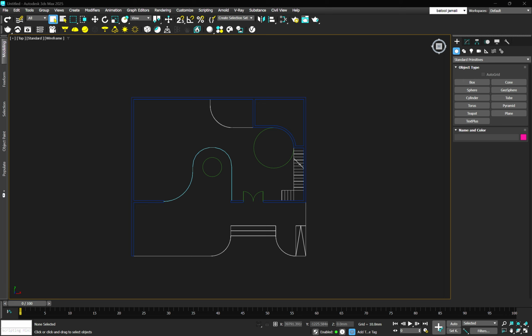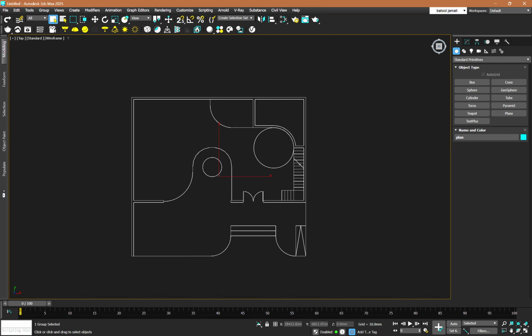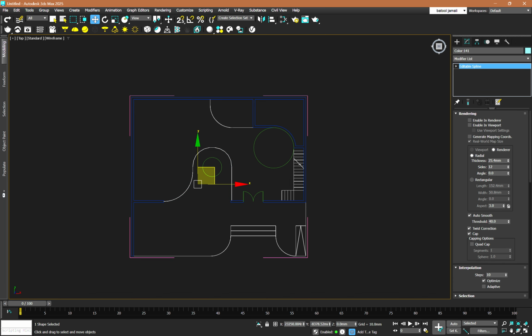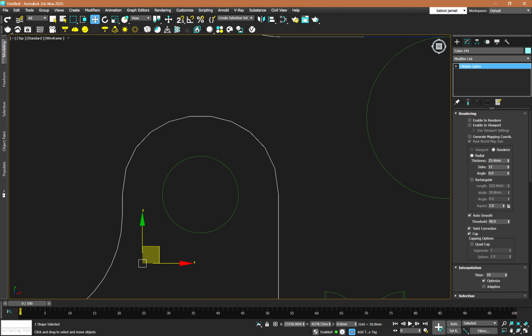Hello, students. I'm getting many questions about lines in 3ds Max and using Snap. So the first thing I would like to tell you is, after you bring in your plan, even if you've grouped everything, make sure that you go and select each line with a curve and make sure that it is adaptive, in order to not have these kinds of broken straight lines. So if I click on adaptive, it will become straight.